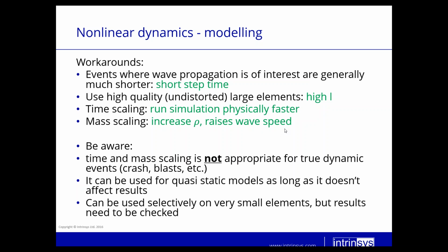So that means you can take higher time increments for the same mesh size. Now, it's very important to be aware that both time and mass scaling are not appropriate if you're running a real-time true dynamic analysis, which is, for example, a crash or a blast type analysis. Where it can be used is for quasi-static analysis.